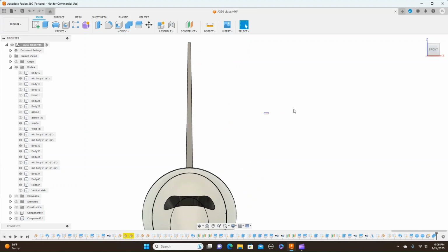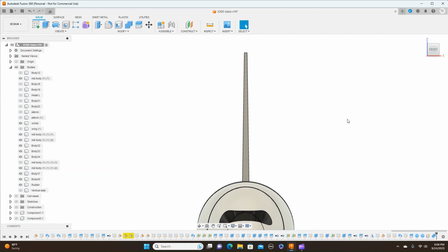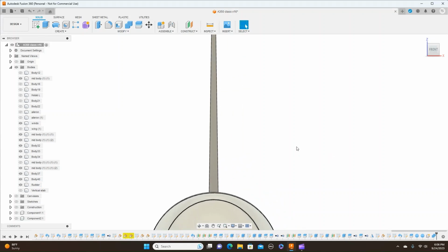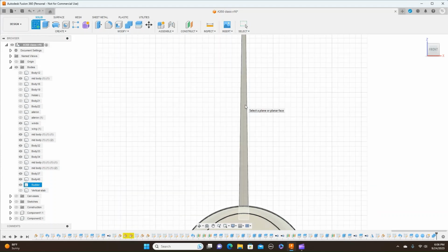And look at the front one here. And I'm just going to draw one hinge right here. And that'll show you how to do it. Then you can just draw another one up here and another one down here. So first of all, come up here to create sketch on this plane.